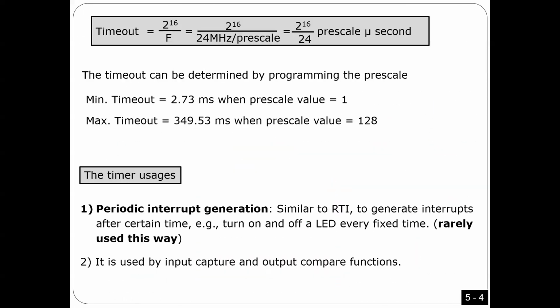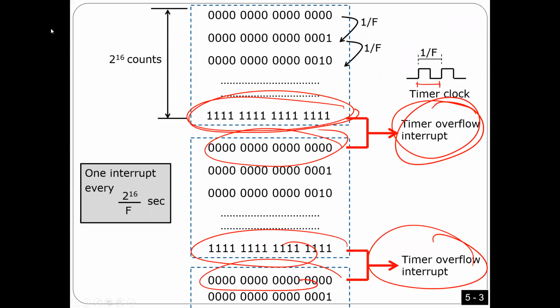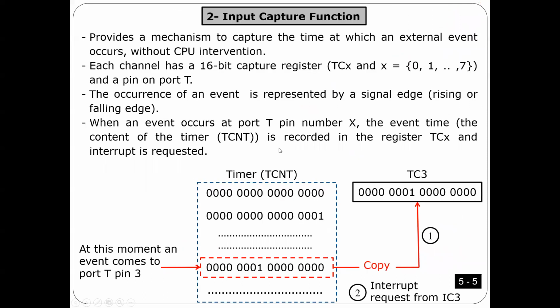Now this is what the timer is doing. All the timer is doing all the time is counting from 0, 0, 0 until 1, 1, 1. And every time it rolls over from 1, 1, 1 to 0, 0, 0, it should trigger an interrupt. That's it, and then it keeps going, again from 0, 0, 0 until 1, 1, 1, triggering an interrupt on each rollover. Is that okay? Great. Until now I didn't explain how it is useful. We have a counter just counting, and we can control the speed of counting. That's all I explained.